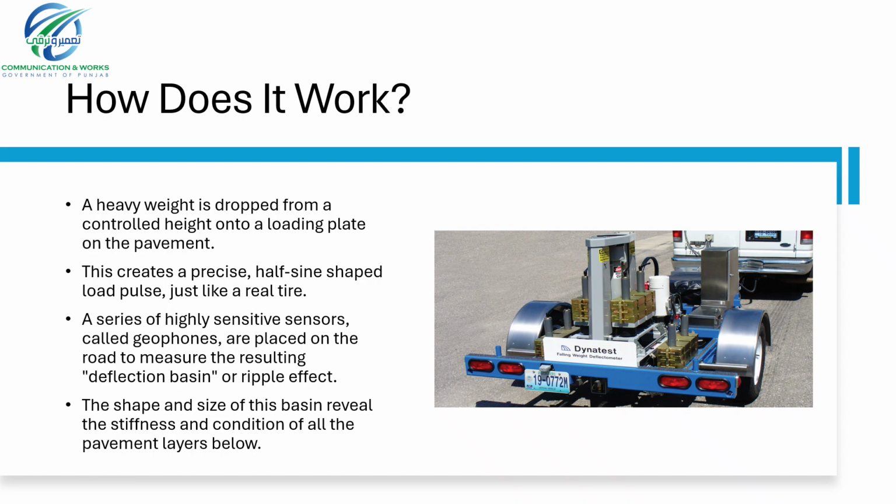a deflection basin. To quantify this response, a series of seismic detectors, also known as geophones, are positioned at specified intervals from the center of the load. These high-precision instruments measure the vertical pavement deflection with an accuracy of microns. The shape and amplitude of this deflection basin are directly correlated to the structural properties of the pavement system. From this data, it is possible to determine the stiffness or elastic moduli of all the individual structural layers, which is the primary objective of the test.